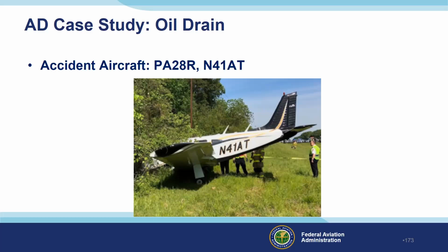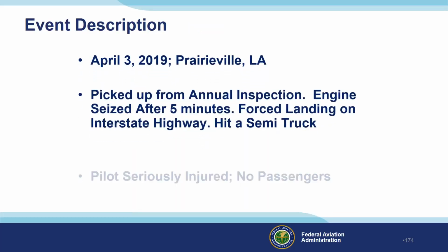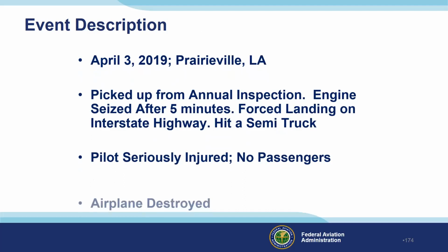Post-accident examination revealed that the engine oil drain valve was damaged when the nose landing gear contacted the valve during gear retraction. This resulted in engine failure due to oil starvation. Further examination revealed that the installed valve did not meet manufacturer specifications.